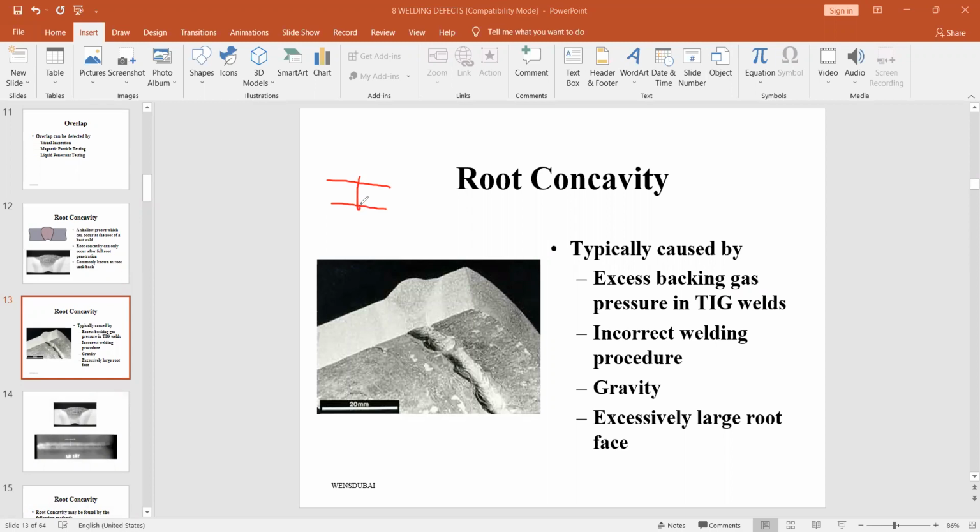Suppose you are doing welding here, and this is one pipe, this is another pipe. Sometimes we send inert gases inside and outside, and those gases will protect your weld metal from the surrounding gases, so you will get fewer defects, or we can expect a weld without defects.